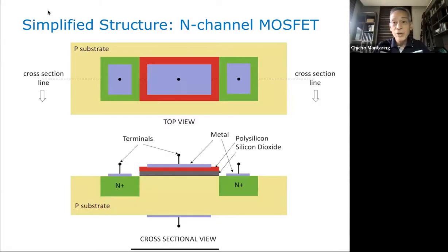I don't know if you attended my lecture where I gave an introduction to the types of bipolar junction transistors. I discussed there that there were 2 types of semiconductors: an N-type and a P-type. In the N-type, your charge carriers are electrons, and in the P-type, your charge carriers are positive charges. So in your N-channel MOSFET, your substrate is a P-type.